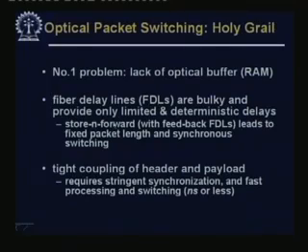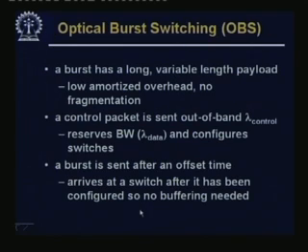That is one thing. Secondly, it is bulky, expensive and not very good. So, fiber delay lines are bulky and provide only limited and deterministic delays. Store and forward with feedback FDLs leads to fixed packet length and synchronous switching. So, because of this, we cannot use simple store and forward. And the other thing is the tight coupling of header and payload, which requires stringent synchronization and fast processing and switching. So, these things are difficult.